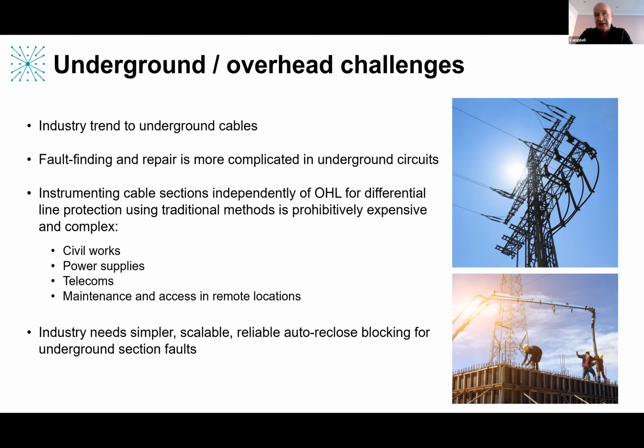And you see here on the final point, we're talking about auto reclose blocking, but of course there are other potential applications if you have measurements at multiple locations on a circuit. And I should say, and I think maybe Philip will pick up on this later, we're not just talking necessarily about measuring current and voltage here. We can measure temperature and other parameters which can be useful, maybe not so much from a protection perspective, but more for monitoring and asset management, integrity monitoring.